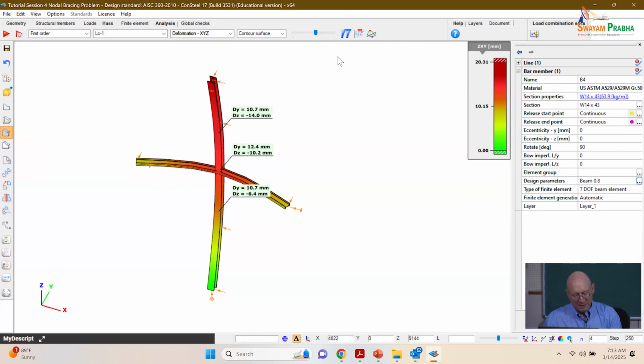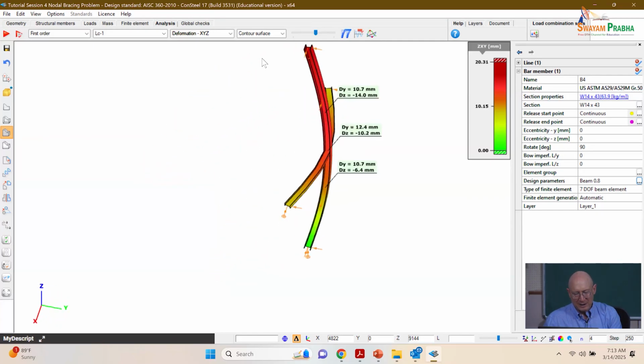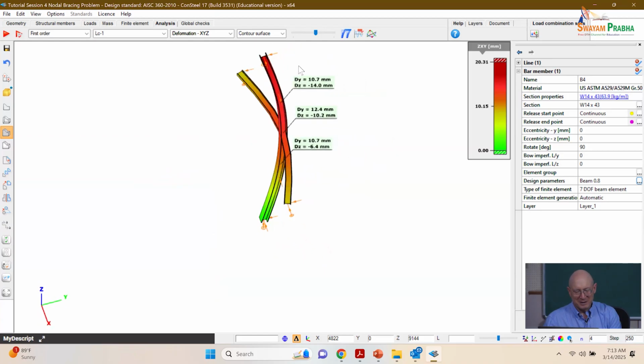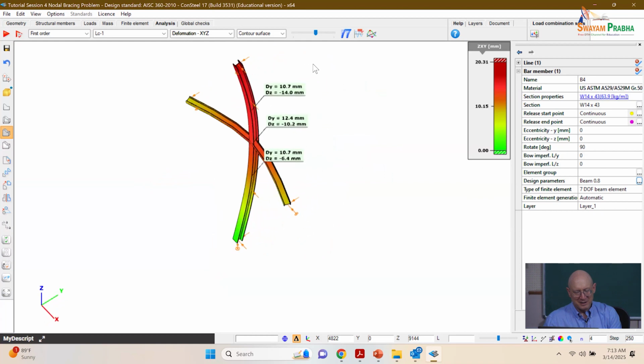It's apparent that I'm getting some help from that flying beam, but it's not really holding that point as if that point were braced, right? It's what we would call a partial bracing to that point. But hey, if I've got some stiffness, and that's enough to where I can make this problem work with a lighter brace, okay, then good. I used 2 sizes smaller on this flying brace.